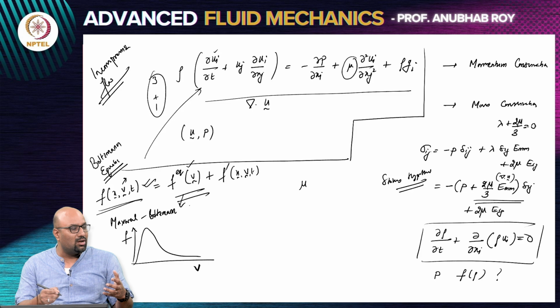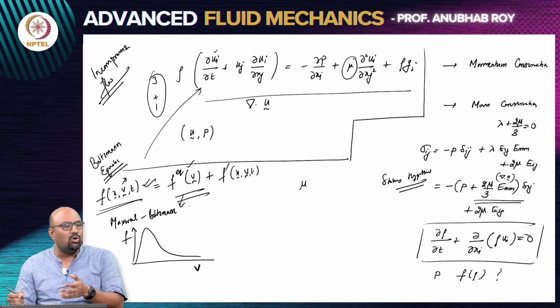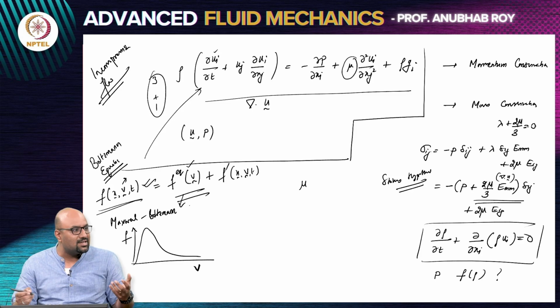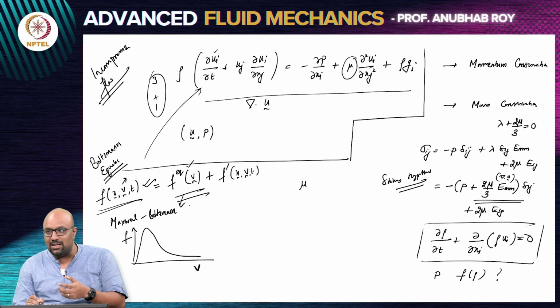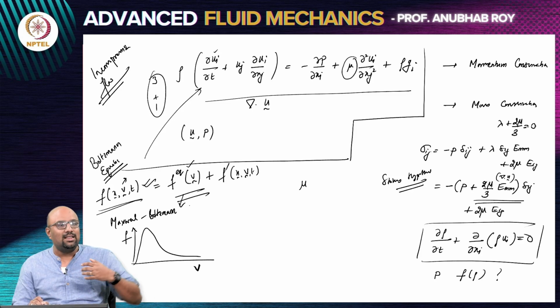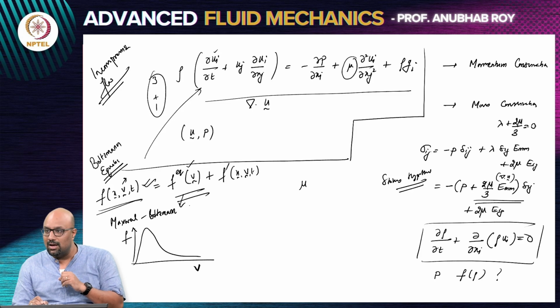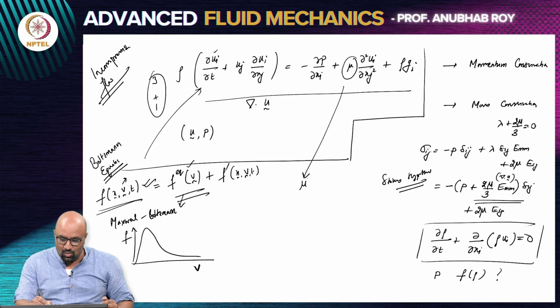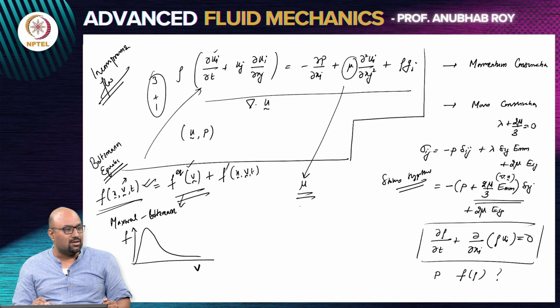So, the same gas molecules where you do PV equal to nRT is the same thing for which you are now doing a dynamics problem, you are writing down a momentum equation. So, it is not like they are different systems. So, when you are doing fluid mechanics, what you are now saying is that the earlier assumption of equilibrium is now relaxed. There is a possibility that they need not follow that equilibrium distribution, and the consequence of them not following that equilibrium distribution is what manifests in one sense in terms of viscosity.